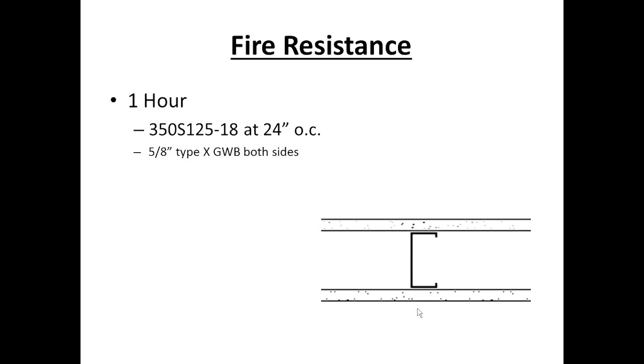The third level of performance is what's called a Type C. All gypsum panel manufacturers make these panels, and the point here is to make sure from a design standpoint that you're specifying the right board. From a distribution standpoint, you're shipping the right board, and from a contractor standpoint, you're installing the right board, because if you don't, you run the risk of negating a fire rating.